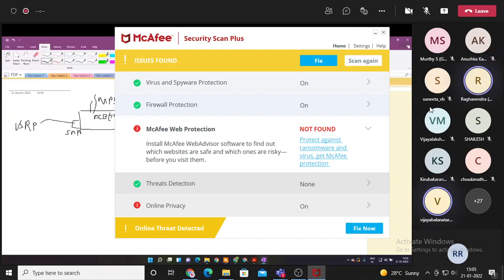This particular PCB takes in your data and it has a threshold. Let's say I'm sending a sinusoidal signal using my USRP. Anything above the threshold, it will switch on. There is an LED over here, because obviously for visible light communication we need an LED. If the value is above the threshold, it will switch on the LED. If the value goes below the threshold, it will switch off the LED. Since we can't have a negative value over here, it is just on and off, which is why we are using an on-off keying scheme. So that is how the transmitter works.